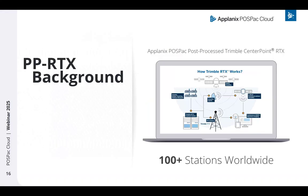One of the core features of POSPac Cloud is the PP-RTX service. Just to give you some background, Trimble has a network of over 100 GNSS tracking stations worldwide, collecting data day and night. All data are processed in a control center, and via a smart algorithm, it creates a set of correction data for the rover, applicable in real time and in post-processing. It relies on a generation of precise orbit, clock information, and atmospheric delay models for GNSS satellites.